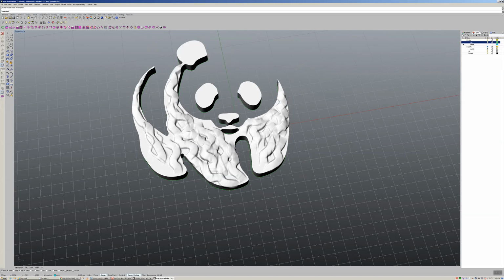And here's one thing that's amazing. In ZBrush, I can't tell what the size of the object is. Here we know it's exactly 50 millimeters. Why is that important? Well, I call Rhino the father of 3D modeling because it gives me my measurements. Whenever you're doing any kind of project, measurements are super important: finger sizes for jewelry, stone measurements, sizing. So I get my basic sizes. Remember, I made that reference square, and that gave me a basic reference. I can go in and out and know comfortably that this will 3D print at 50 millimeters, because Rhino is my safety net.